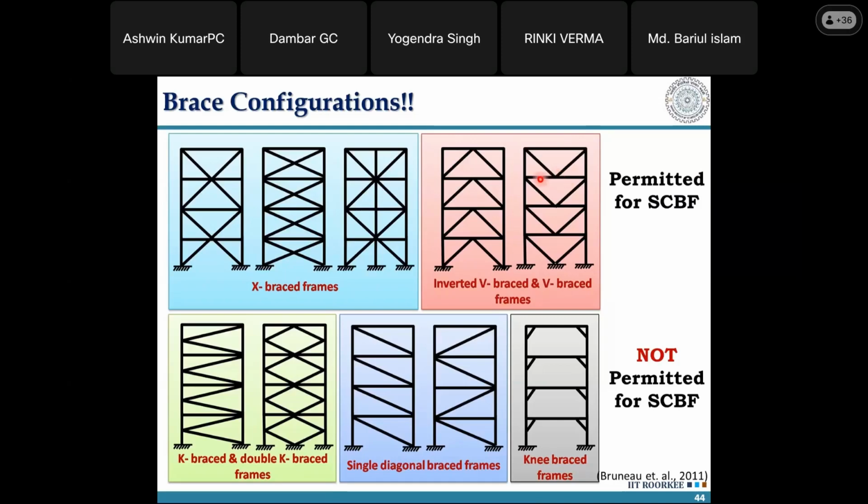So the beams and columns should be good enough to carry the combos related to gravity load. For the earthquake, you can bring it on after that to design your braces, and then again check the size of beams and columns as per global and local analysis. Right? I hope you have understood. That is what the code says. Our code doesn't mention it specifically, but if you look at 341.16, it says that do not take the advantage of the braces for the beams and columns to carry general gravity load, because once the earthquake happens, there may be major damage in the braces. It may fracture, it may not fracture, but the beams and columns should be good enough to carry the gravity loads.